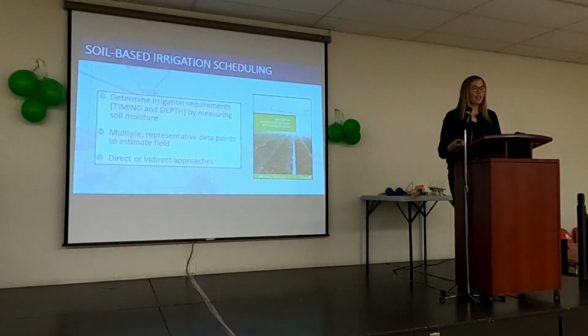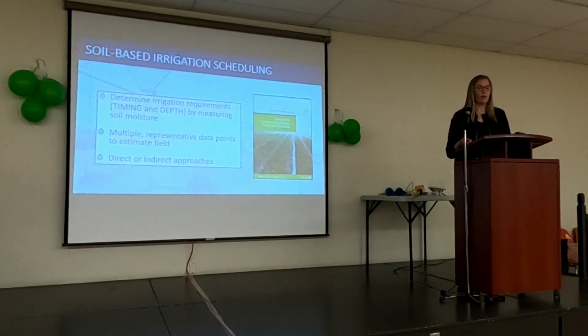Soil-based scheduling is just one of three approaches that you can use. Evan already went through weather-based and plant-based. But this method is exactly what it sounds like. All we're doing is monitoring the soil moisture and then determining the irrigation requirements, which are going to be the timing and the depth of application.